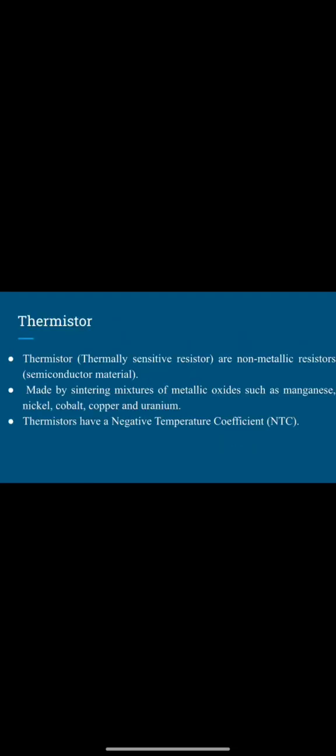By selecting the right materials, there are very temperature-sensitive devices that are useful in temperature control circuits and for temperature measurements. The thermistor, also known as a thermally sensitive resistor or non-metallic resistor, is made of semiconductor materials. Thermistors have a negative temperature coefficient. It means that the resistance decreases as the temperature rises.